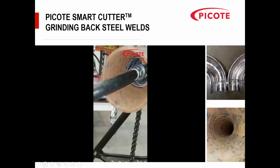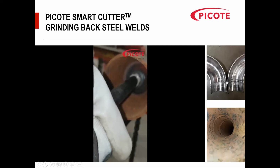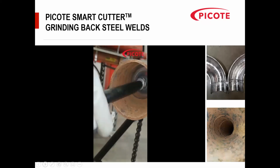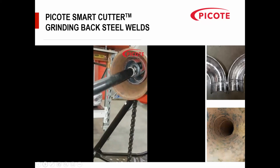And the power of it is that we were asked by a company that does a lot of steel fabrication. One of the problems is when you weld the steel pipes, you've got that internal bead. And when that internal bead is on a bend, it's very hard to remove. So they approached us, and they then brought the smart cutter, just purely, as you can see here. As it's rotating, the grinding panels come out, and very aggressive. And like I said, you can see on the photographs on the right-hand side that it ground away the complete weld on the inside to make the pipe smooth.